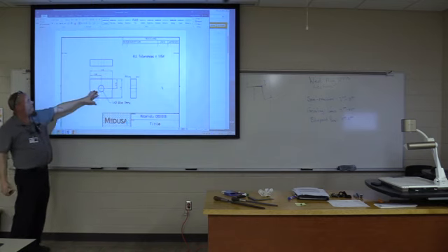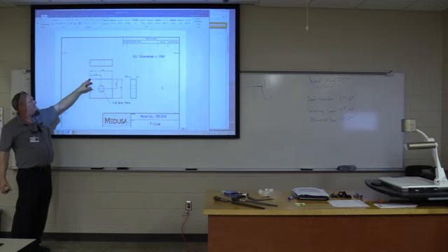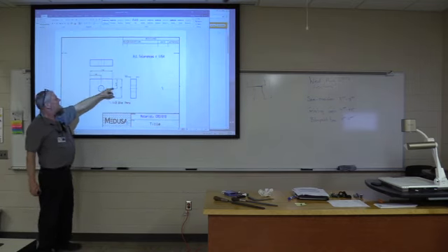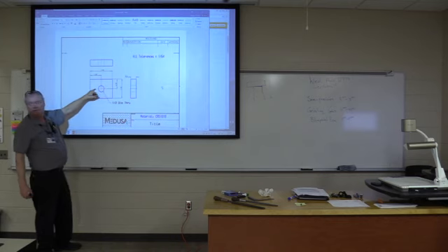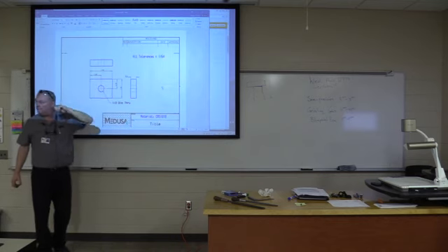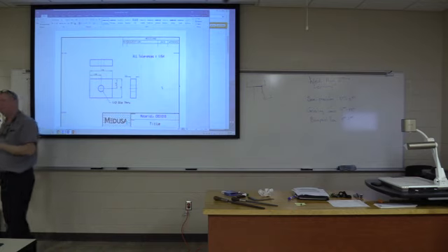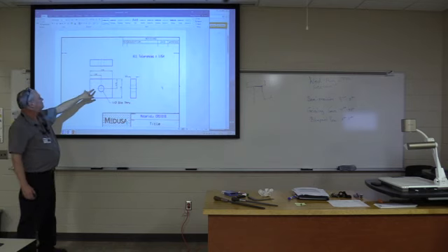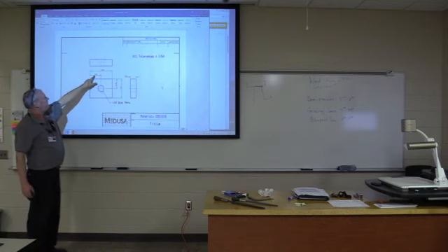But all we're going to need you to do is, from one particular corner of the part, to measure and inscribe these dimensions into the part. You're going to prick punch it, you're going to center punch it, and then we're going to drill the hole. And what I want you to be able to do eventually is to hold about 15 thousandths of an inch.